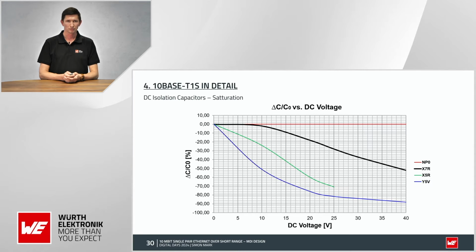But the problem can appear here. Every capacitor has some saturation. After some voltage is on the capacitor, it saturates according to the line. We have in most cases X7R material for the capacitors, which are used for these SMD capacitors, MLCCs.